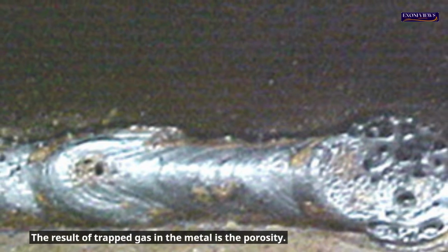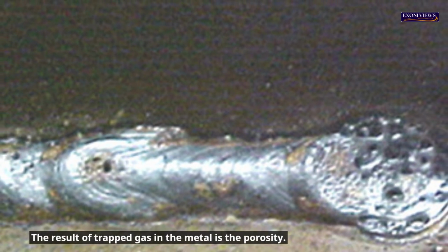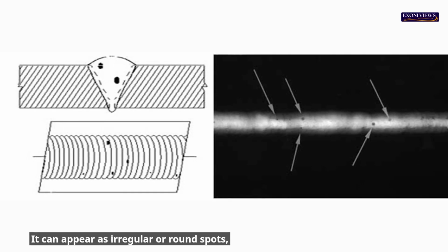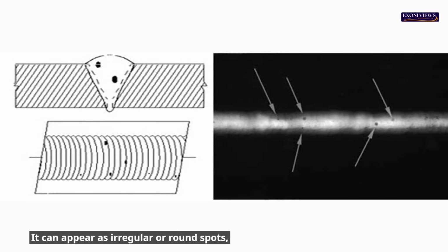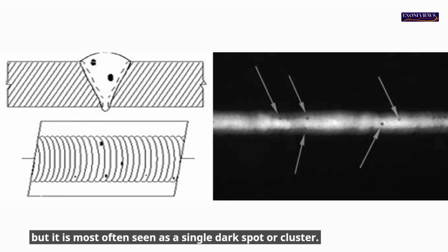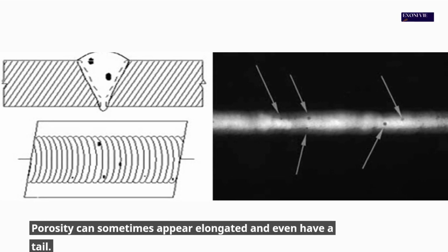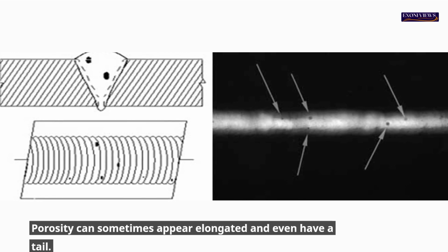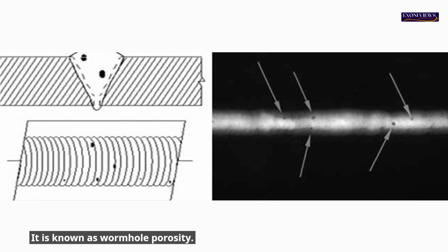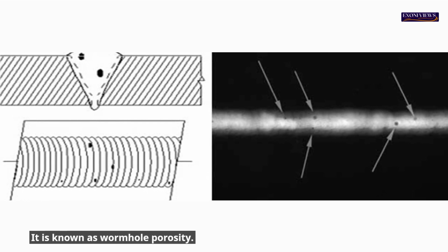Porosity. The result of trapped gas in the metal is porosity. On a radiograph, porosity appears in many different shapes. It can appear as irregular or round spots, but it is most often seen as a single dark spot or cluster. Porosity can sometimes appear elongated and even have a tail. The gas is trying to escape from the metal while it is still liquid. It is known as wormhole porosity.